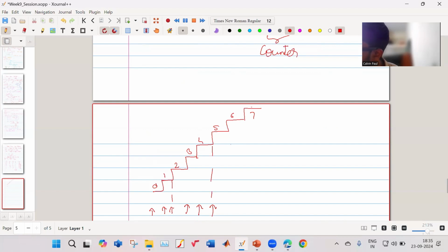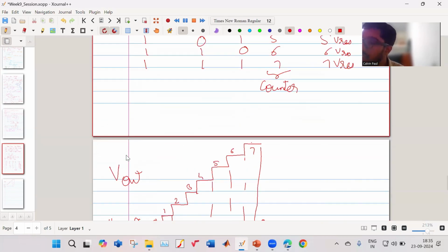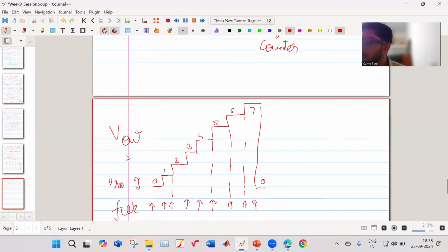At the clock event it steps up, and then this finally goes back to 0. So this is my clock, this is the V output of my DAC, and this magnitude is V resolution. So this is how our DAC will generate an output. Any queries in this part?